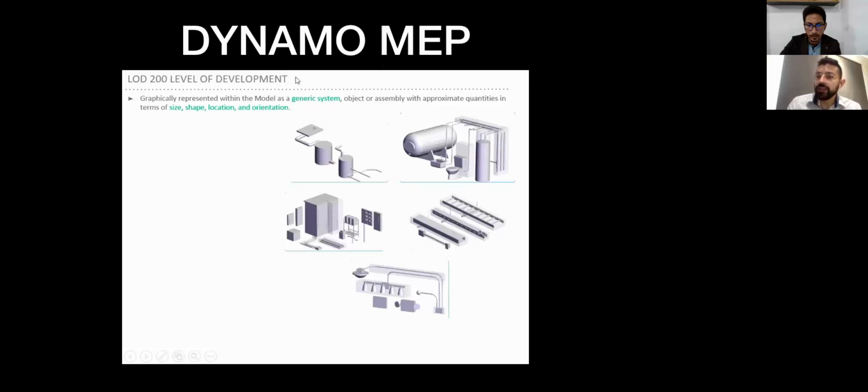If they haven't, now you can get into the terrain of using Python to find out how to get those elements out from the Revit API or from any other API that you want. Perhaps you want to connect with Project or Primavera, or to use Forge or something that goes on the web. You can use Python there. All the nodes that have been created are working on Python.